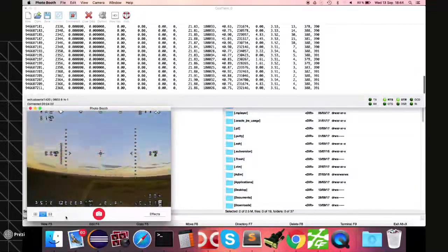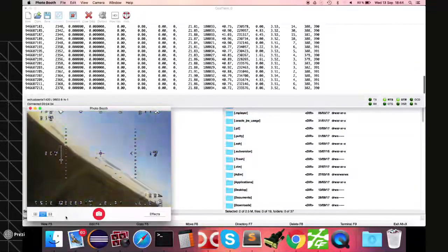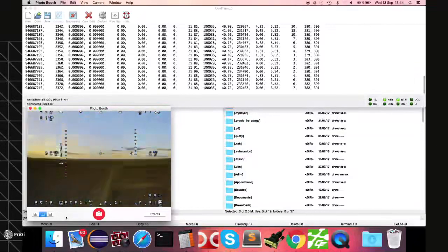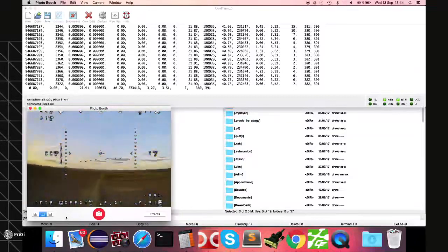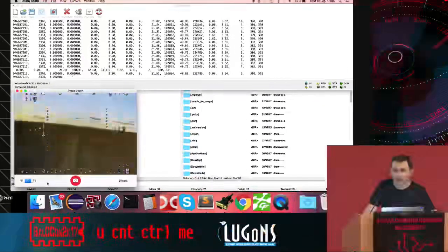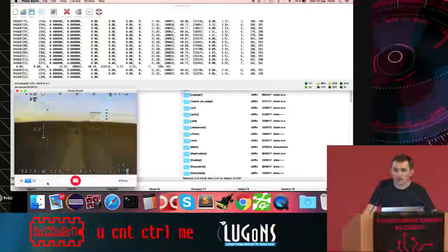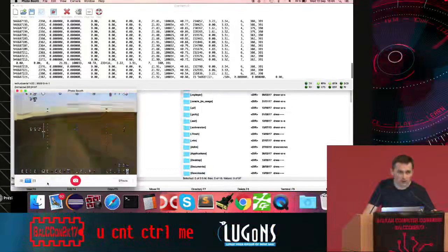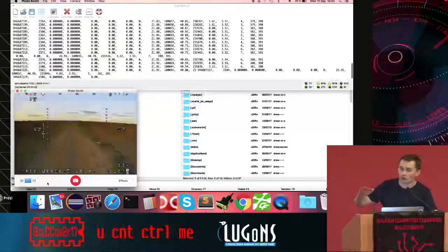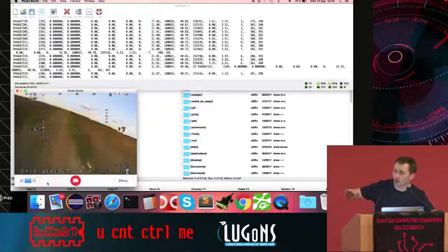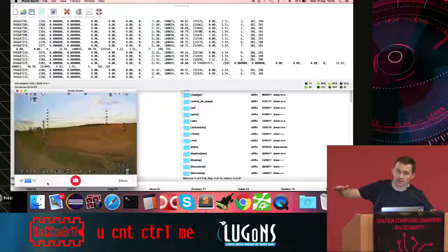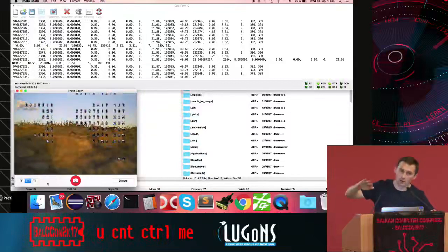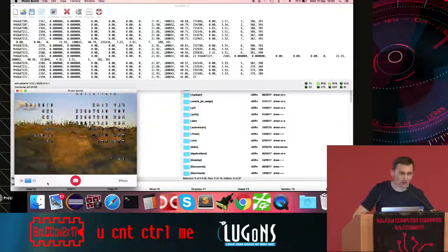And what you can do here is to actually configure the speed of the compensation. So this is why it's shaking. It's doing it improperly. It's doing it too fast. You need to do it slower. So instead of it going like woo, woo, woo, it goes nicely like woo, and stays there. And if needed, only goes back. But here, it oscillated like that.